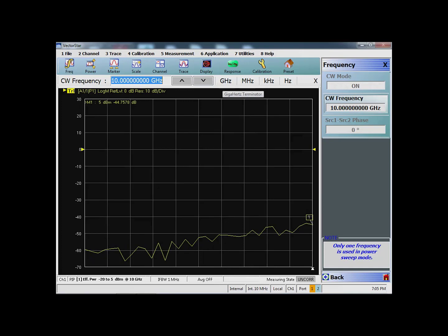And you will see that now we are seeing the transmit side test receiver A1. But for us, what happens is that it goes through from the A1, which is the transmit side test receiver, then it goes through the DUT, and then it goes to B2. So for us, it's also important to see what is happening on the receive side of the vector network analyzer.